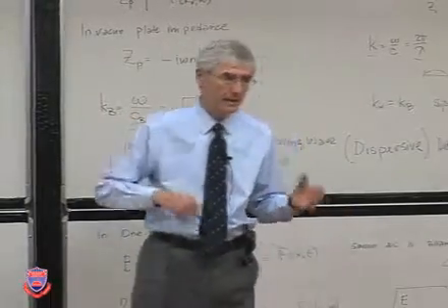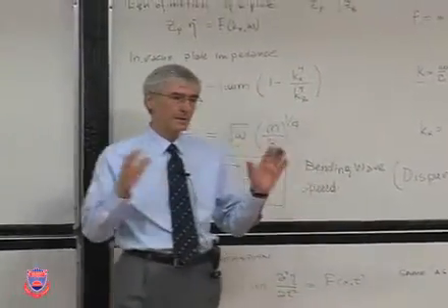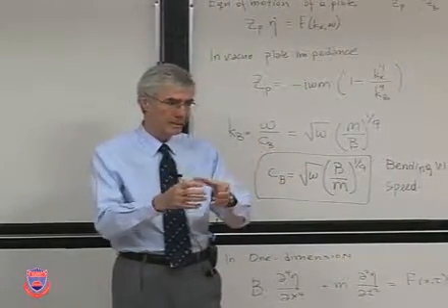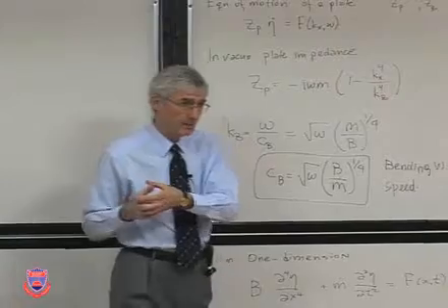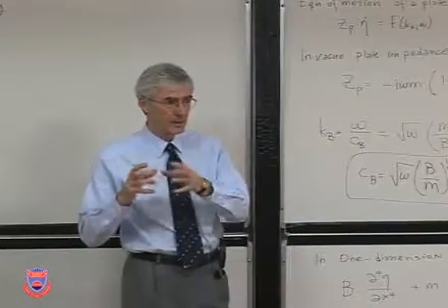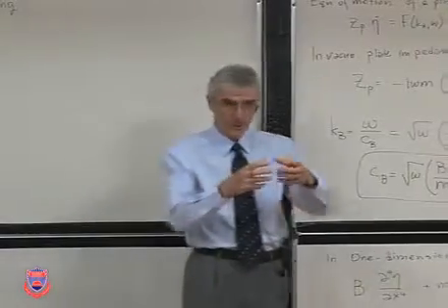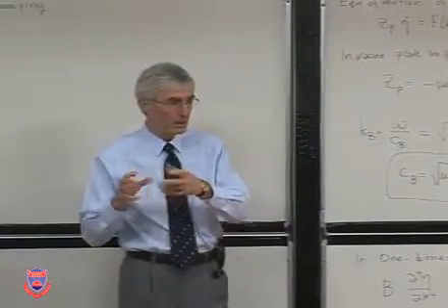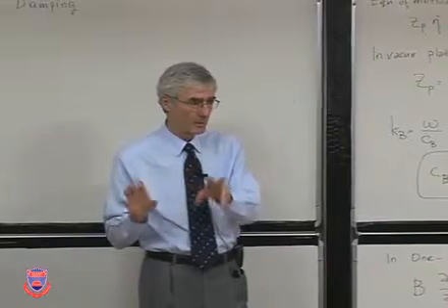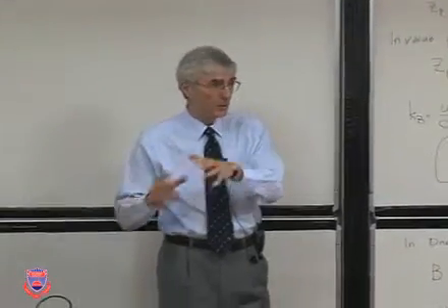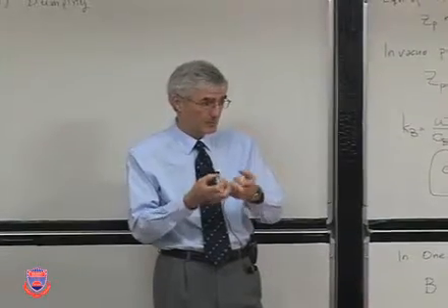Exactly. Okay. That's the fundamental mechanism of damping. It dissipates an ordered energy into disordered energy. By disordered, I mean molecules that absorb that kinetic energy that's normally a usable energy into thermalized motion of molecules, whether it's in a fluid like viscosity or in a solid that becomes warmer.